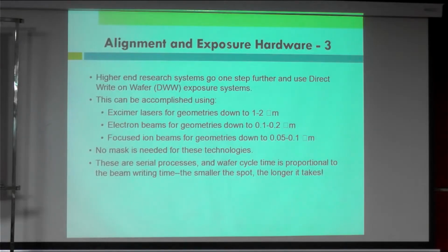Higher end research systems go one step further and use direct write on wafer exposure systems. This can be accomplished using laser, with a geometry of 1 to 2 micrometers, electron beams for geometries down to 0.1 to 0.2 micrometer, and focused ion beam for geometries down to 0.05 to 0.1 micrometer. In this case, no mask is needed for this technology. You just expose the laser or the beams directly. It's a kind of writing directly on the